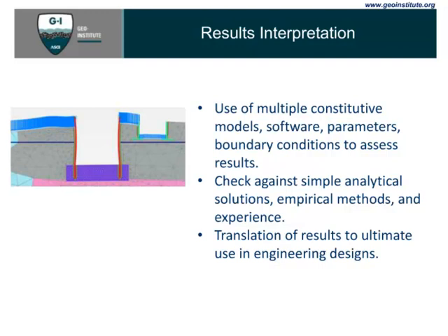You can run multiple constitutive models if you're not sure you're running the right constitutive model. Some people will even run their models in one software, and then they'll take one or two key cases and run them in a completely different software package to see if they get similar results. You can vary parameters just like you would in typical analytical engineering situations. That can be harder with finite element analysis because it's more time intensive to run separate models over and over again.